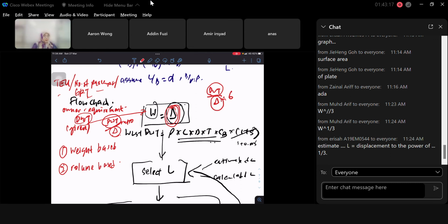Yeah, they are weight based and also volume based design. So weight based usually is for ships carrying heavy cargo, yeah: tanker, bulk carrier, general cargos. But volume based is based on volume. Yeah, the container, the passenger ship, the ro-ro, ro-pax vehicle. So the volume is more important than the weight.